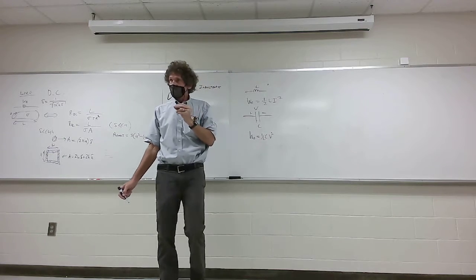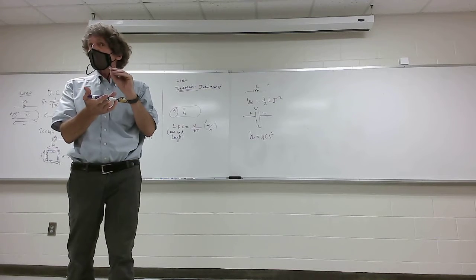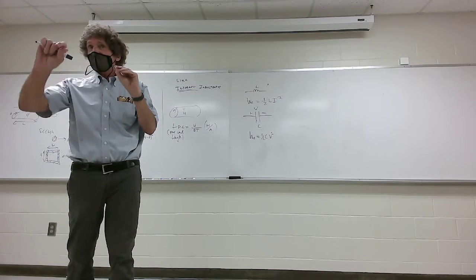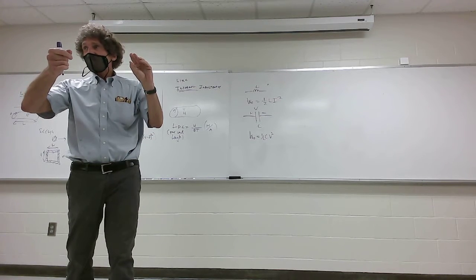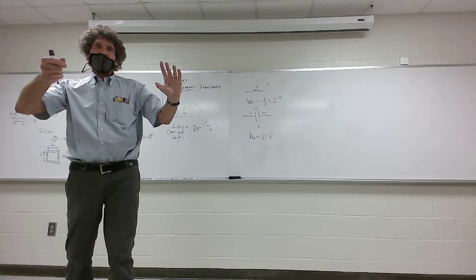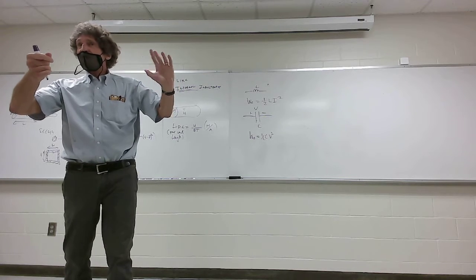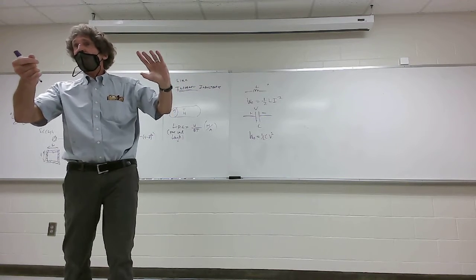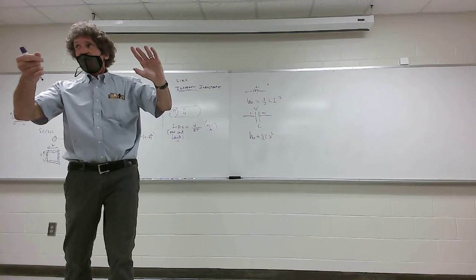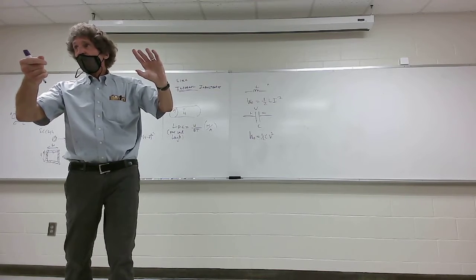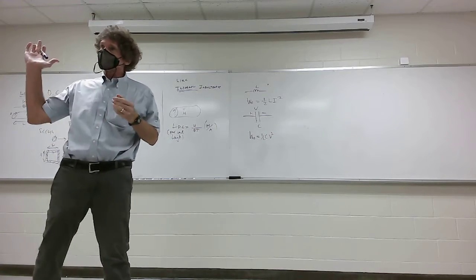Now, these supercapacitors that they have can store a fair amount of energy. The real thing is that you can short these things. Like when you start your car, you need a lot of current, right? Well, if you had a capacitor that had only a 12-volt breakdown strength, roughly, a little more than that, and you charged it so it had maybe 10 times the charge you would need to sustain 100 amps for a couple of milliseconds, you all see where I'm going with this? Then starting your car when it's really cold, because your lead acid battery can't crank, would be a benefit. That's what they're doing now. How many know this?